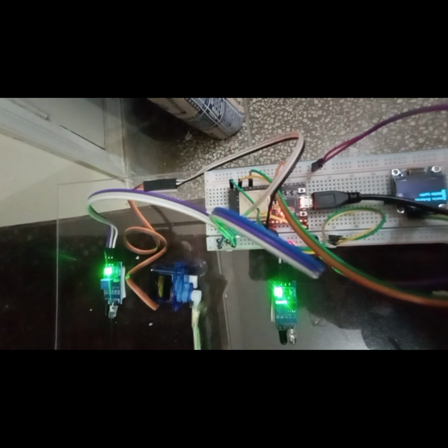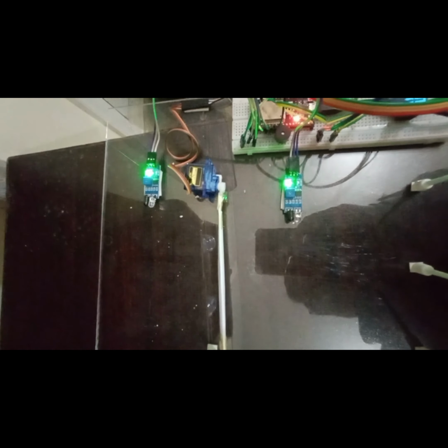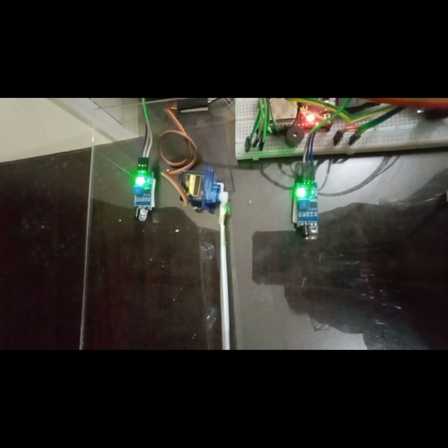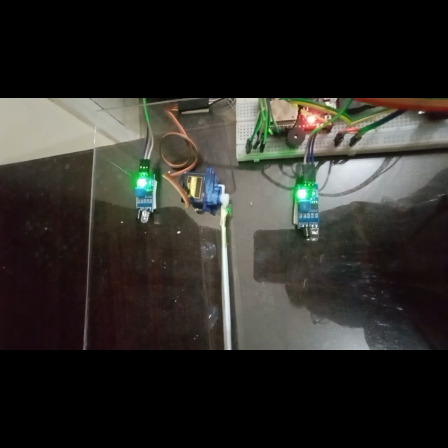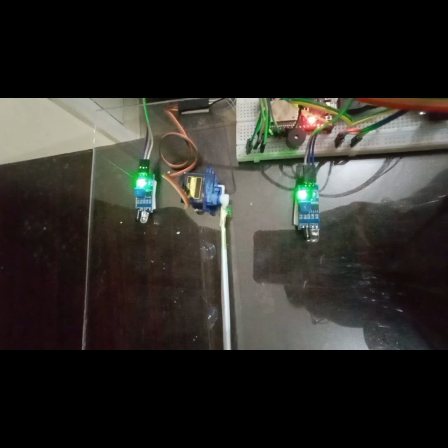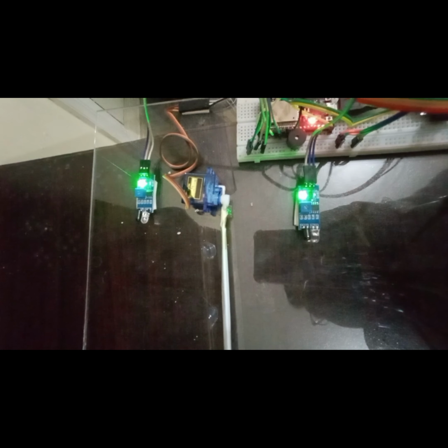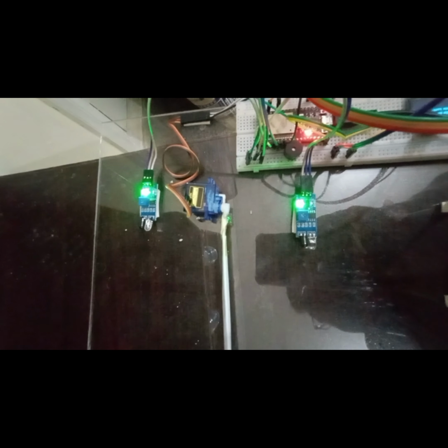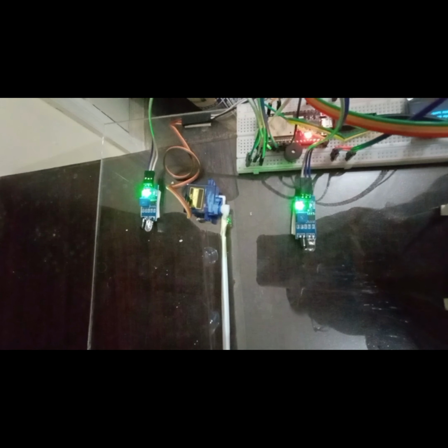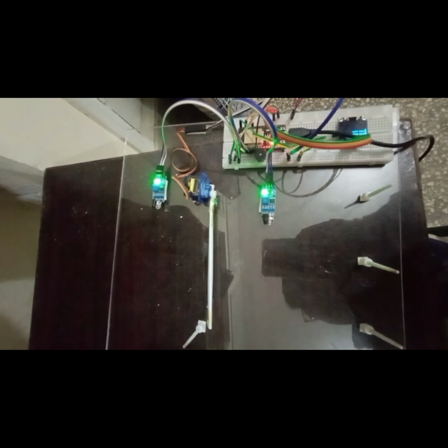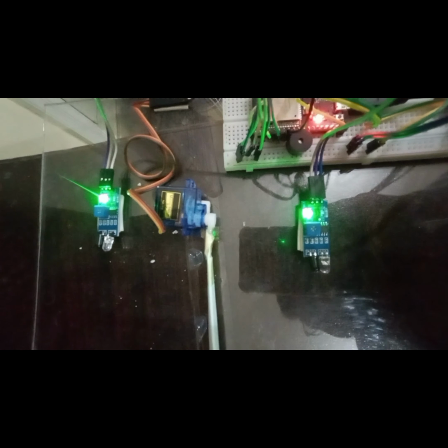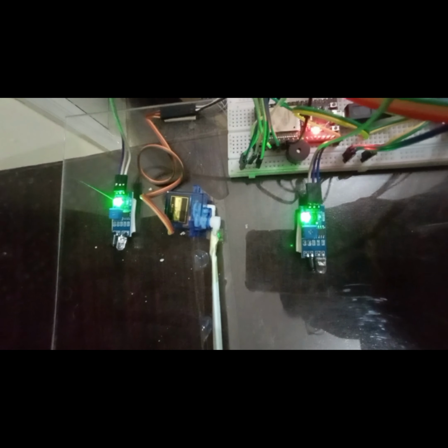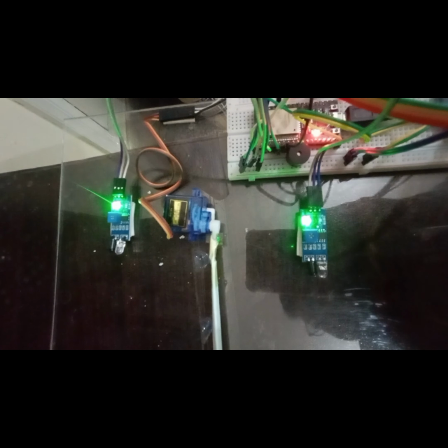Now afterwards we will move up to infrared sensors, which are used for entry and exits of people or ships. The TCRT 5000 infrared sensors detect when someone enters or exits the area. These sensors trigger the door control based on movement, ensuring smooth operation. Afterwards, we will move to servo motors, which actually control the door. The servo motor controls the door, opening when someone enters or exits and closing after they pass. Its precision allows us to automate the door movement seamlessly.